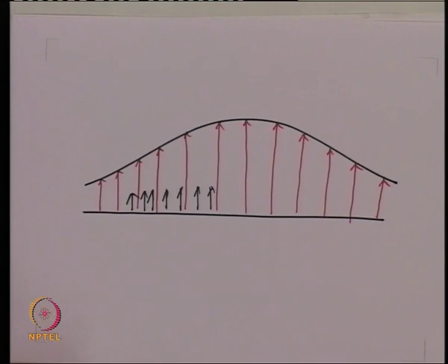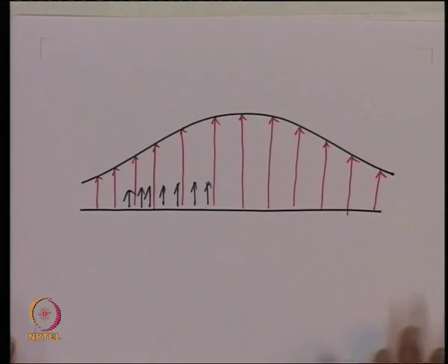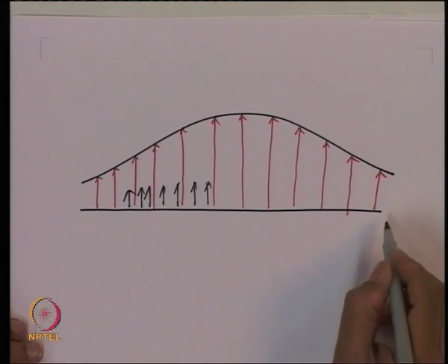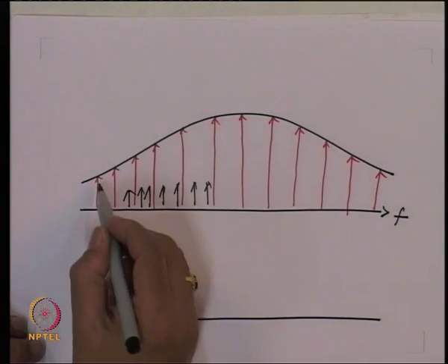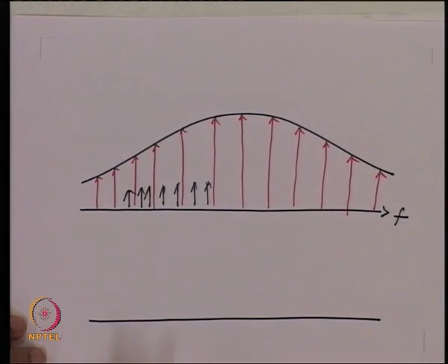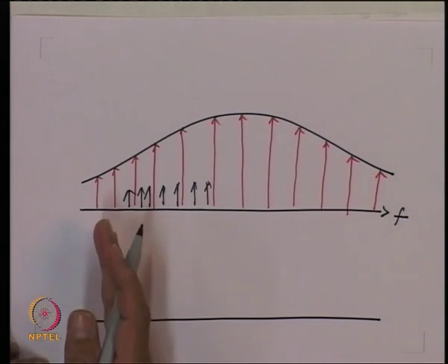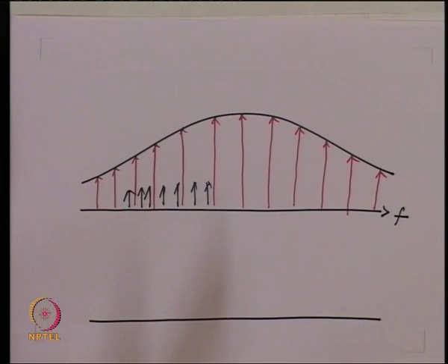Now if I try to see this in terms of the time domain, it will become immediately clear how the pulse will get broadened. So this was in terms of frequency. If I modulate this light with, let us say, a pulse, and see in terms of time how the pulse would look, initially when we transmit all the pulses riding on different carriers, they will be located at some location here on the fiber, and all of them will be aligned in time.